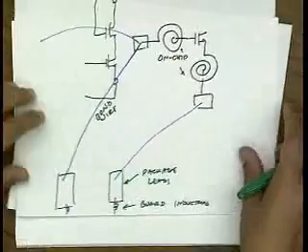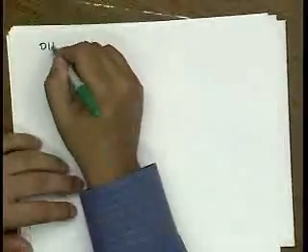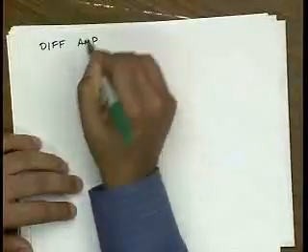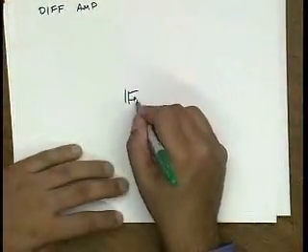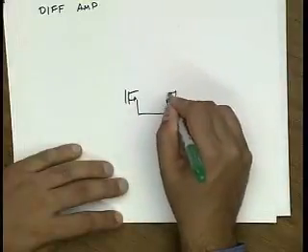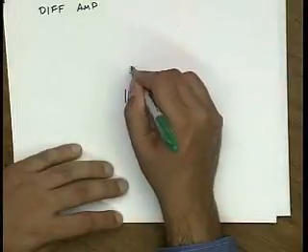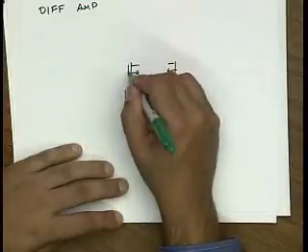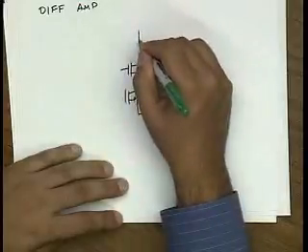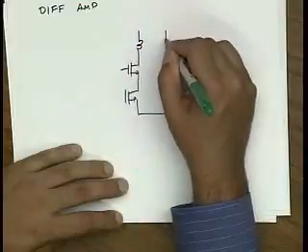Another option is to build this amplifier differentially. So let's look at that and why that helps. So a differential version of this amplifier looks something like this. Again, we're going to use a cascode topology. We're going to use some on-chip inductors as the load.